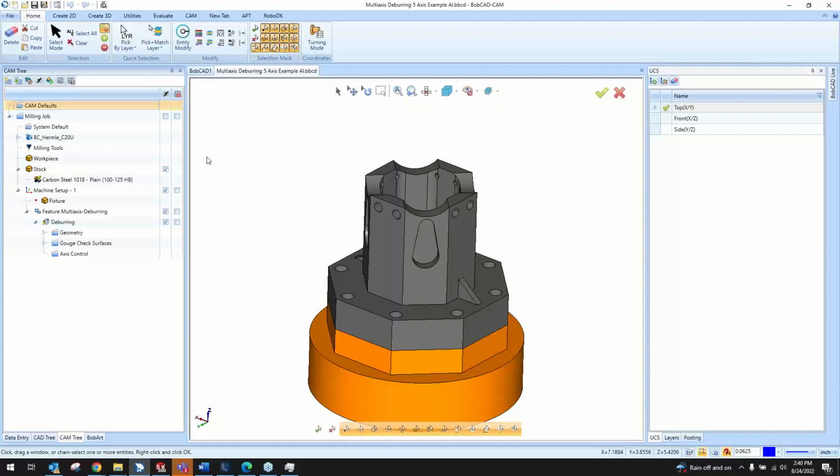If we're going to a more shallow location, we can do just a drill operation. If when it calculates the depth it's any further than that, it will do a pecking. So a lot of default settings that we can set up for the hole recognition page. So we've got a lot of things to default with that.